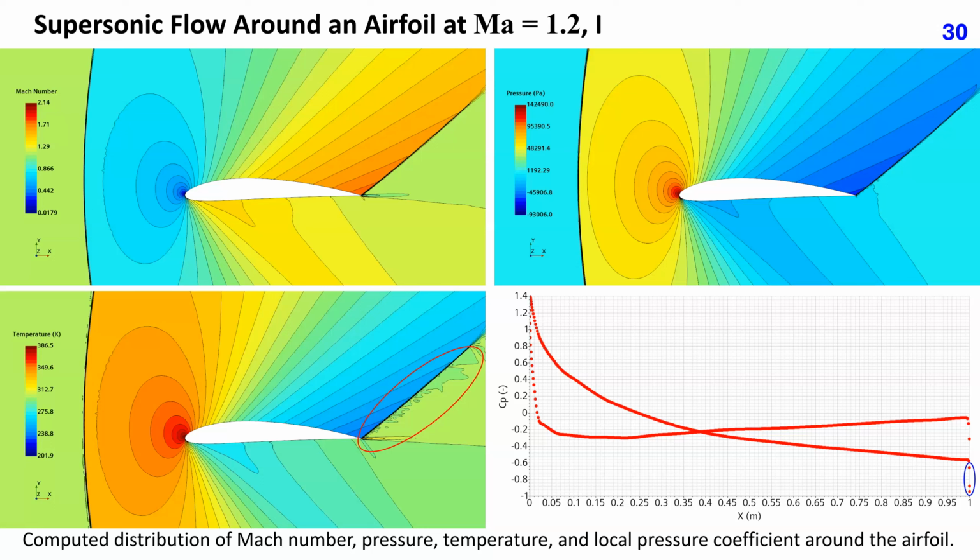In the case of a supersonic flow at the free stream with Mach number 1.2, 2 shocks are present in the flow field. One is circa half a chord length ahead of the leading edge, and another on the suction side right at the trailing edge. Simulation was again first performed using the grid shown in slide 22, and then locally refined in zones where the shocks were identified.